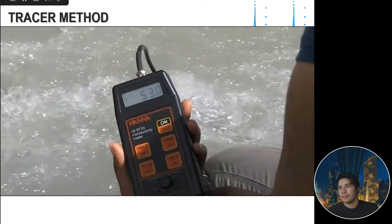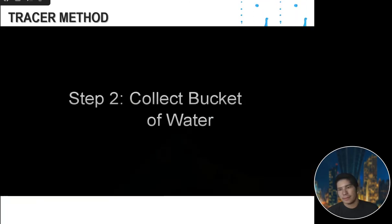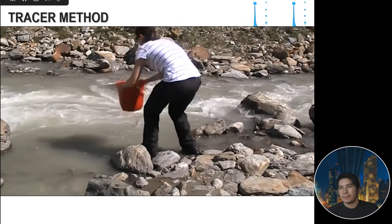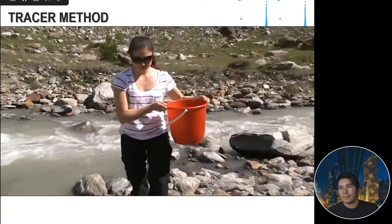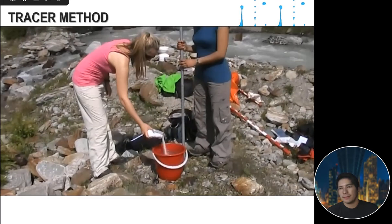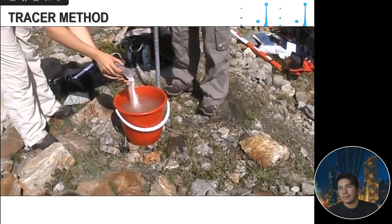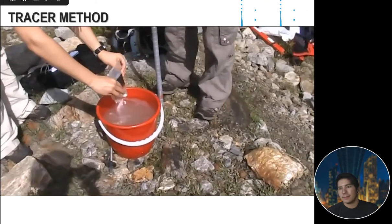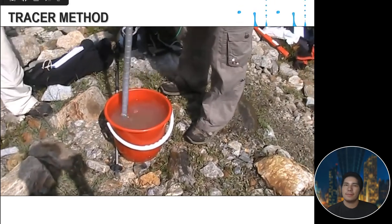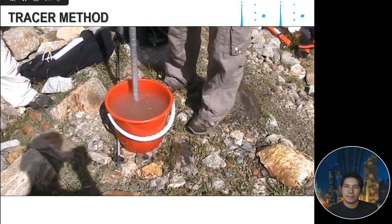The first thing you need to do is to measure the electrical conductivity downstream. You will need to collect a bucket of water, like you can see Lucia doing here. You then need to dissolve a known quantity of salt into the bucket of river water that has been collected. Here you can see Rachel adding 1 kilogram of salt into the bucket of water. In order to ensure that the salt is dissolved fully, you should stir the mixture thoroughly, as you can see Summon doing here.